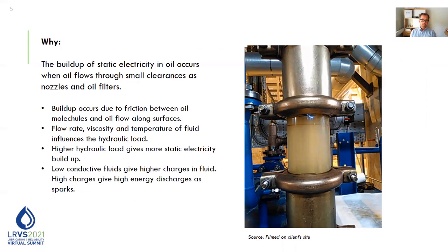The buildup occurs when oil flows through small clearances such as nozzles and oil filters, and that's because of the friction between the oil molecules themselves and between the oil and the surfaces. Flow rate, viscosity, and temperature of the fluid influence the hydraulic load. Higher load gives more static electricity buildup, and low conductive fluids like lube oils give higher charges. Higher charges give high energy discharges as sparks.